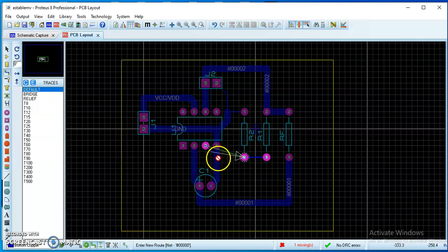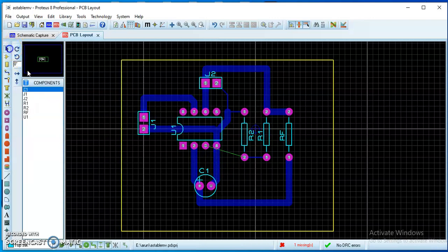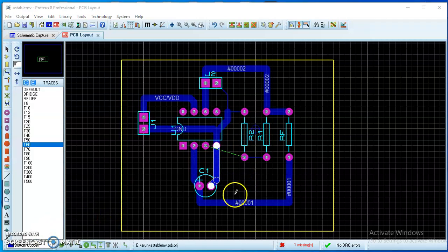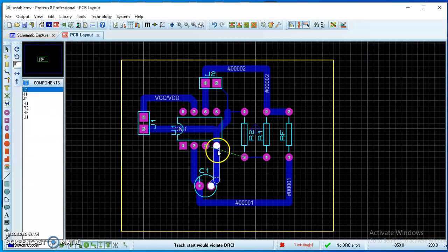Okay, so the blocking track is this one. This is the problem. So we need to change this path through some other way. Again, we can think how we can do that. What I got is we can change this path, this one. We can take it through some other way and connect it between 3 and 2. So what I am going to do is I will take this path through this resistor or under this resistor.